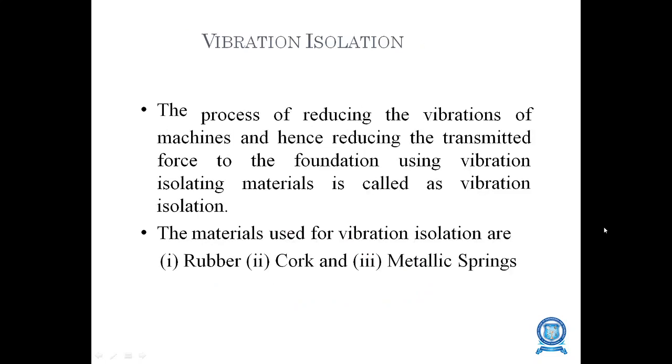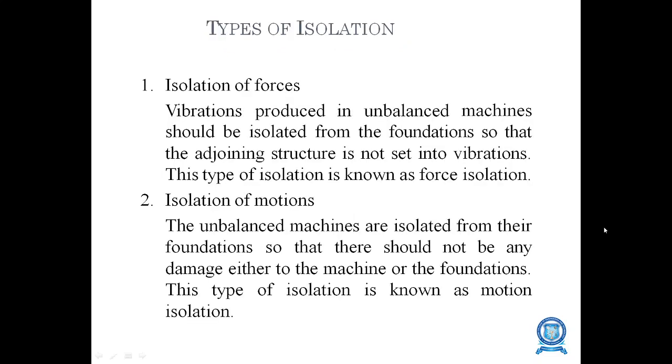The process of reducing the vibrations of the machines, and hence reducing the transmitted forces to the foundation, using vibration isolating material is called vibration isolation. Some of the materials used are rubber, cork and metallic springs. There are different types of isolation.